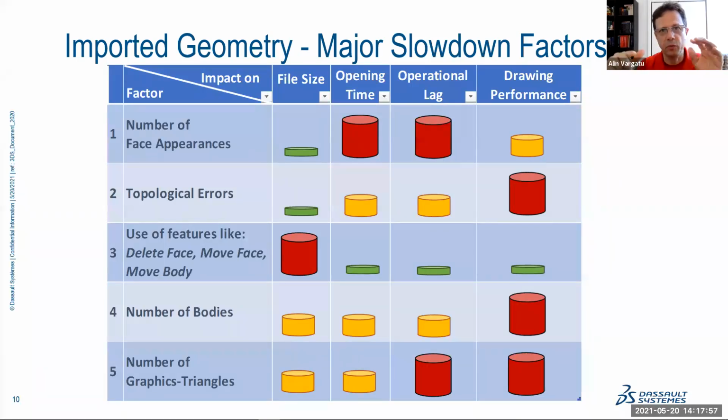So it's going to have the edges computed based on the sides of the graphic triangles that are on those faces. And that destroys the functionality that we are so proud of now, called detailing mode. Because instead of having a clean edge to which it's easy to attach information like this edge belongs to this face belongs to this part belongs to this assembly, if you put a balloon, this is going to be balloon number 73. If you select the edge, you can dimension it. Now there are going to be a bunch of little triangles all over the place.